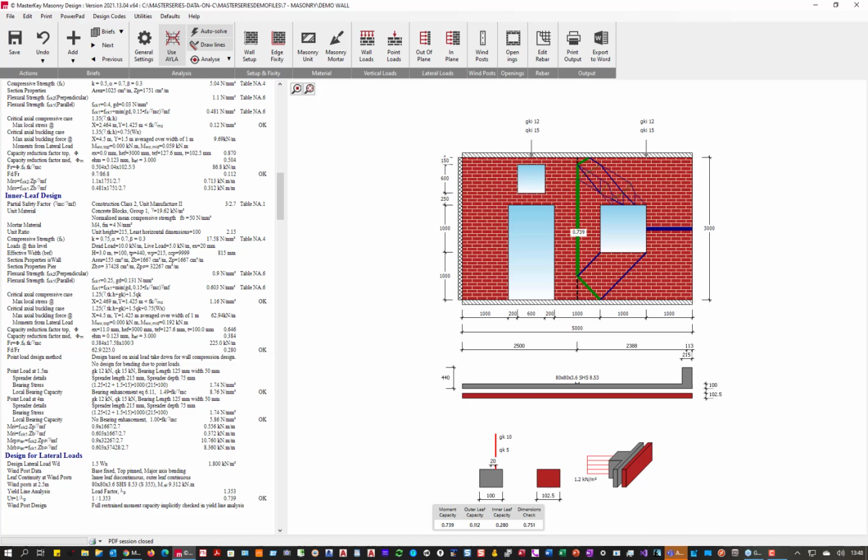Also, as I had mentioned earlier, the use of 1 or 2 courses of engineering brick instead of a DPC works very, very well. The very high strength clay bricks look nice architecturally, marking out the bottom of the wall, but they also usually provide a reasonable degree of prevention of water ingress.